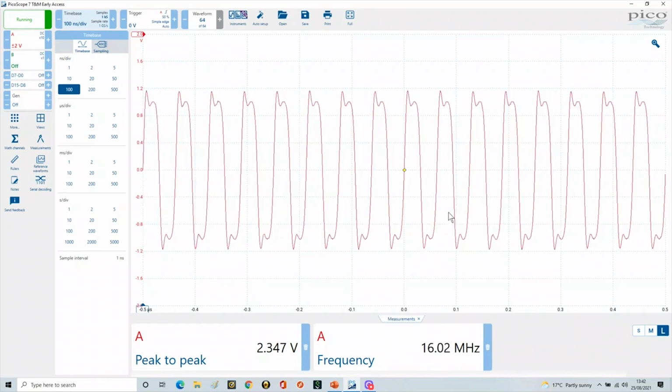peaks. And this is partially to do with the fact that we're getting the close harmonics. This is 16 megs. So if we times that by 3, then the next harmonic is 48. So 48 megahertz is the first odd harmonic. And so there's our fundamental at 16 megahertz. So the part of this frequency in here will be sitting at 48 megahertz. And